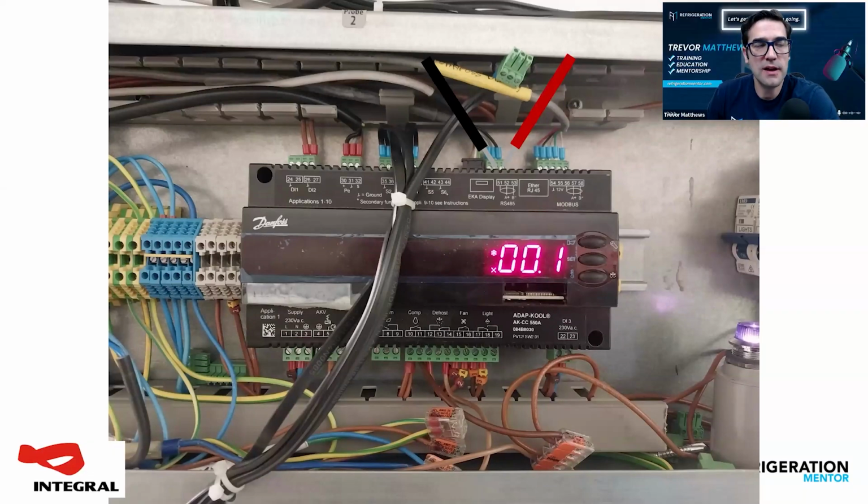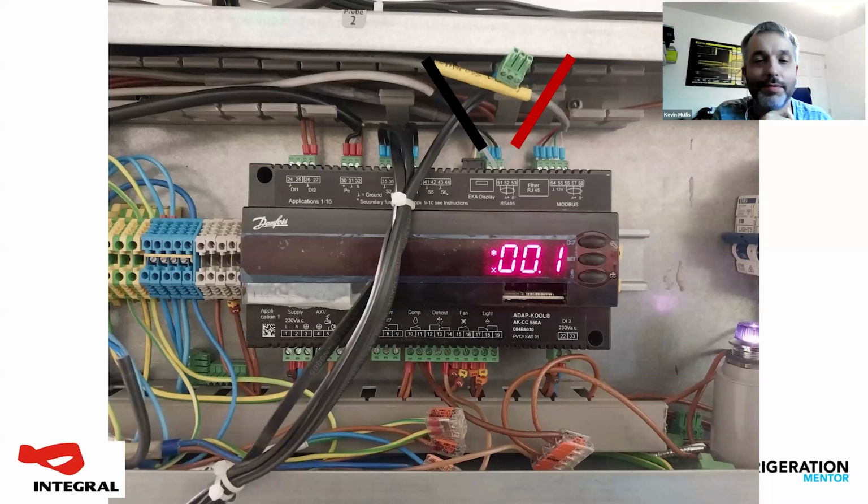Yeah, and that's a good thing. I didn't have the slide here, but that's exactly right. Pull it off. Am I getting the 5 volts out? If you are, then it's the transducer. I've seen this countless times on CO2 systems where people are changing parameters or replacing components, when in reality it's just a pressure transducer that is faulty. Yeah, it's more often than not something it's using to calculate the superheat or the case temperature that's gone faulty rather than the controller.